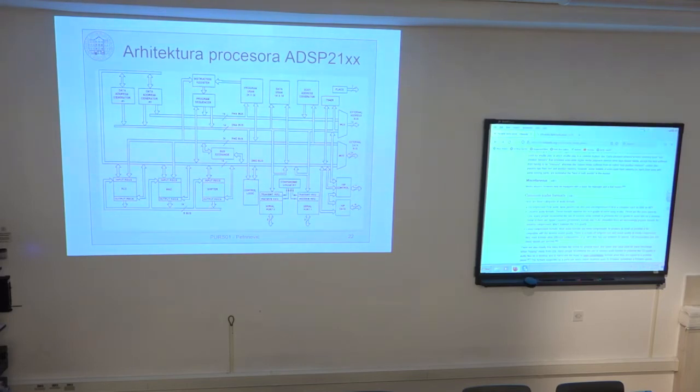Okay. Just as a remark, there are alternative architectures of DSP processors which are trying to actually employ all of the executional units at once. So in this case, they have a really very wide instruction word. The abbreviation very long instruction word, VLIW, is used to describe this architecture. These DSPs have instruction words which are 128 bits wide or even 256 bits wide, because they want to really employ all of the executional units at once.